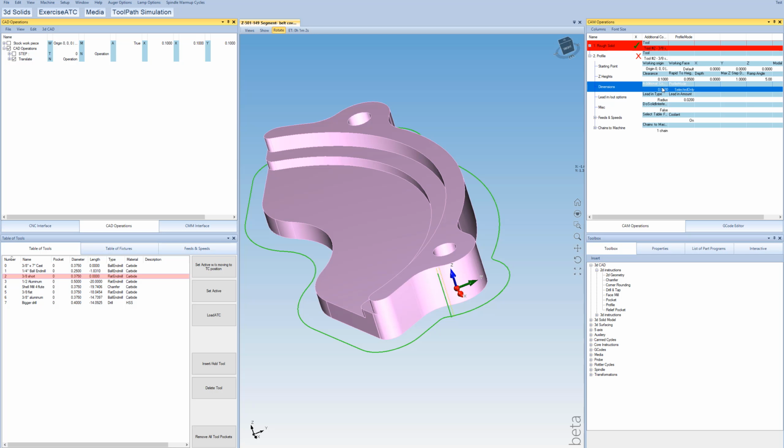So now we just have one more step right up here to do. And for this one, it's actually too small to do a pocket routine on because the 3/8 is much larger than this width right here. So we just go right to a profile cut, basically the same routine as what we did for this outside cut. We just do it on this inside right here. So let's comment this one out here. Okay, and insert, oops, not a pocket, insert a profile.